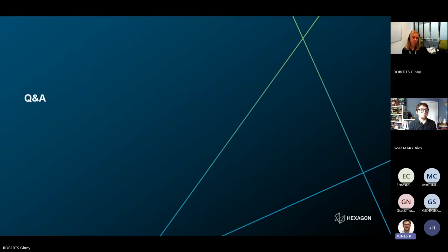So we can also take the Romax model, which is often simulated in the static environment. So we're just looking at static deflections around a given load case. But we can export that to Adams View, I should say, to look at how the system might perform in a transient or time domain approach. If you imagine you've got gear changes within your system, you can see how those changes in the operating conditions of your gearbox affect the load spikes in your system